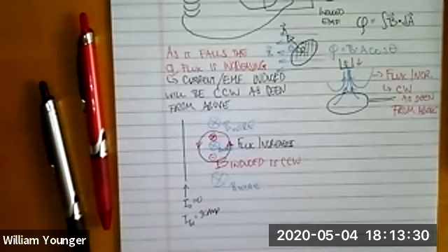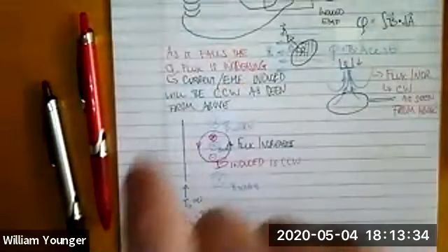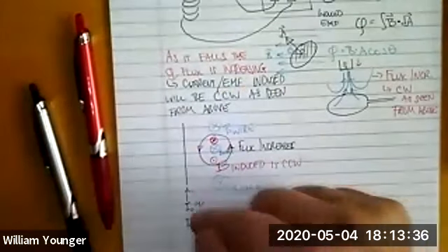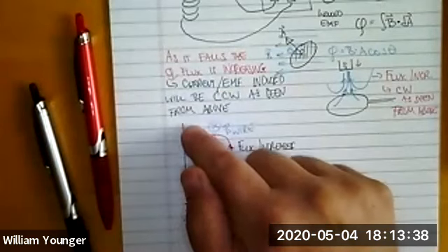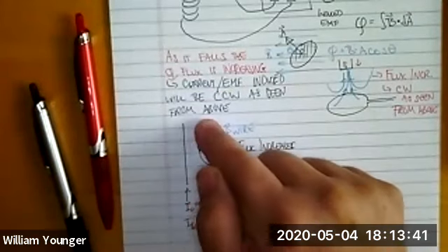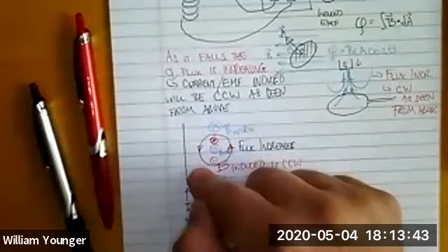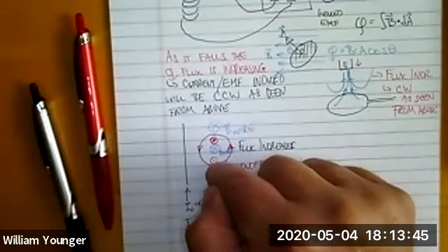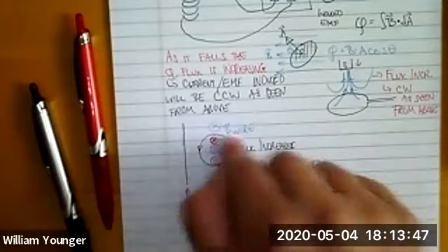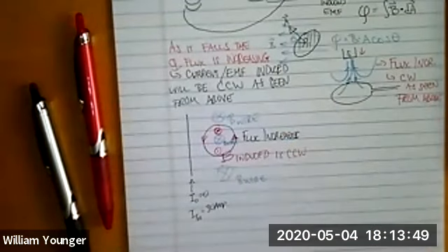So now it's going to try to create a magnetic field going the same direction, which means all of a sudden it's going to go clockwise. So if I switch the wire from 30 amps to 0, while it's ramping down from 30 amps to 0, the current produced in here would be going clockwise now. Isn't that wild?